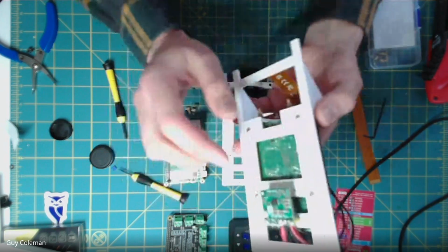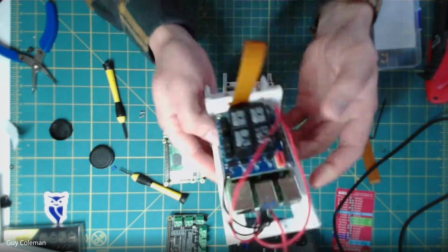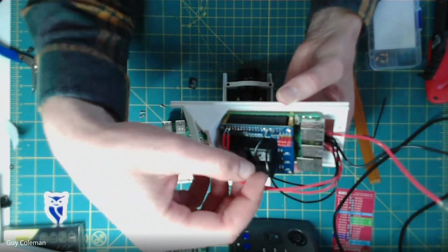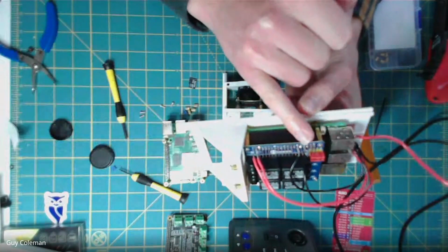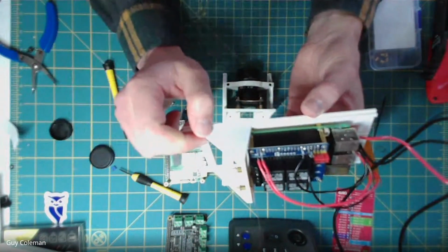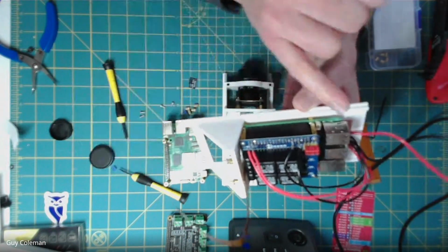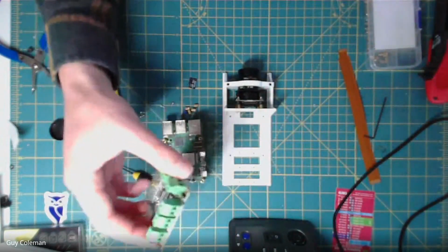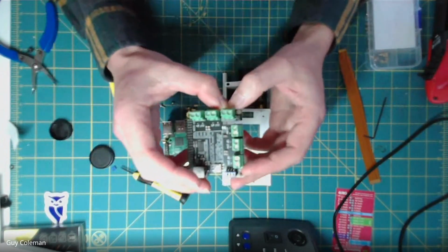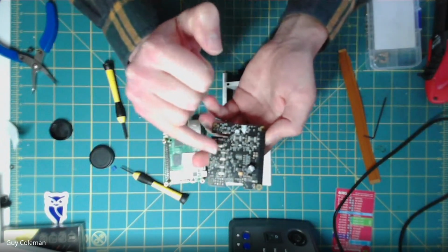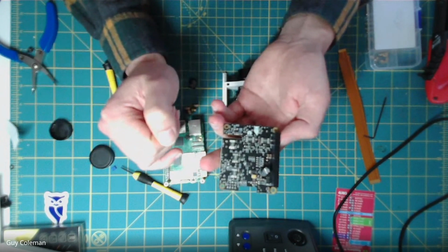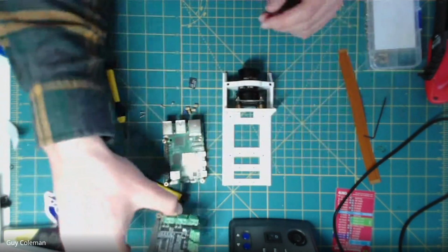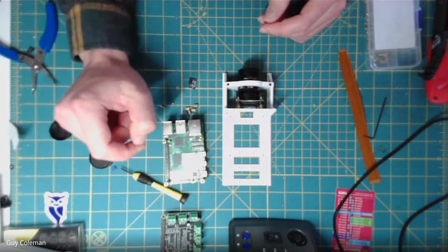The problem with that, though, is you will need to add the power supply and then wire that in, as you can see here. If you're using the Raspberry Pi 5, because it's a 5 amp input, you do need to supply power over 2 sets of 5-volt pins on the GPIO. This is all explained in the instructions on the GitHub repository. That's the benefit of this HAT, though, is that it combines all that together. So you have transistor-based switching, rather than electromechanical relays, so it's faster and nicer, with less noise. It also combines all that together.